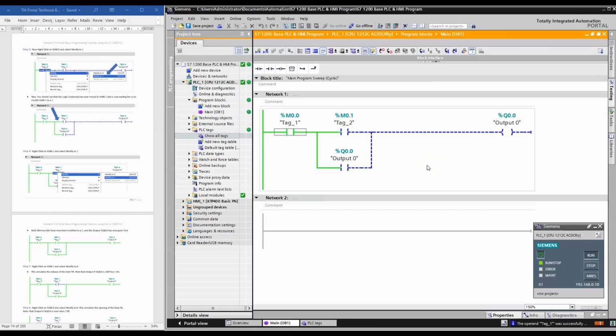Nice. Okay, so PLC SIM in this instance is awesome because I can physically toggle the bits and modify them from a 0 to a 1 and see how my PLC program is going to react to it. So that means that my stop push button is fine. Nobody's pressed that, right? So there's voltage going in to the stop push button. That means that this is true.